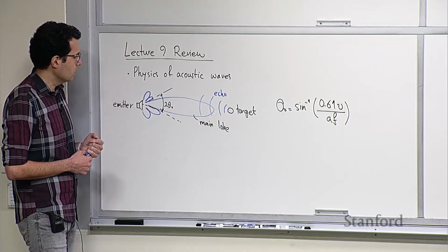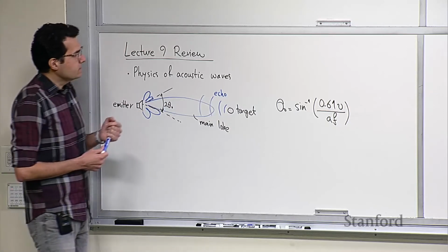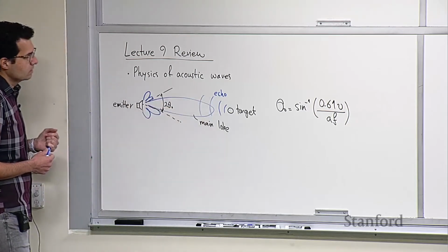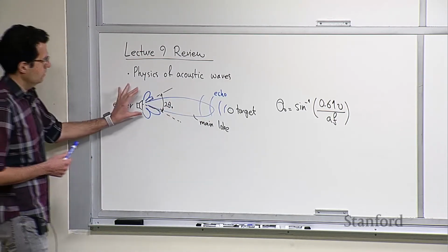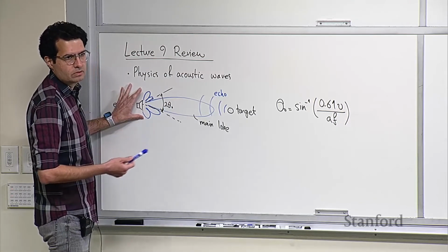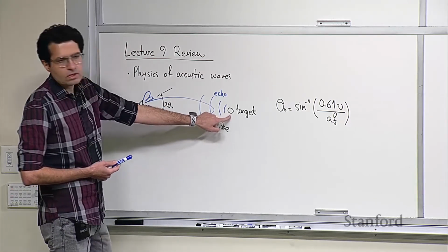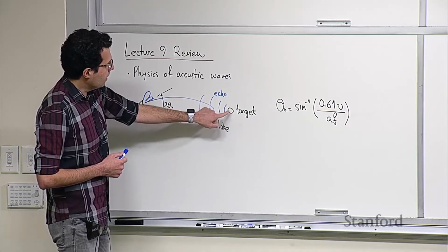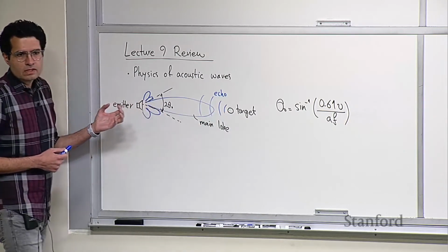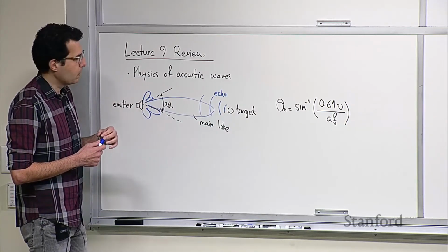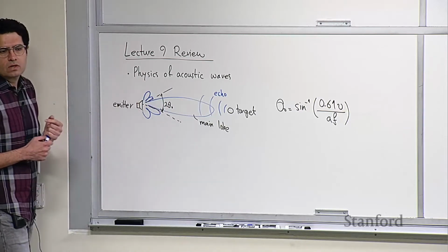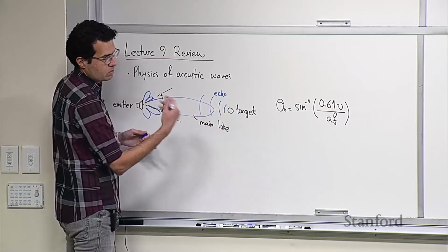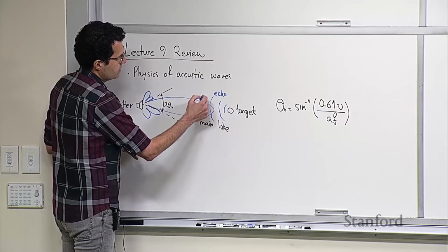Then, of course, we are interested in the echo, not just what we transmit, because we need to process the echo to do sensing with it. And so we continued along those lines. We said, okay, you send an ultrasonic wave according to this radiation pattern or beam pattern. It hits a target. If you assume your target is small, this is just an assumption for us to be able to simplify the math, the return echo can be very well approximated with spherical waves, okay? So you hit it with a focused beam, but what echoes back to you, you can estimate as spherical waves.